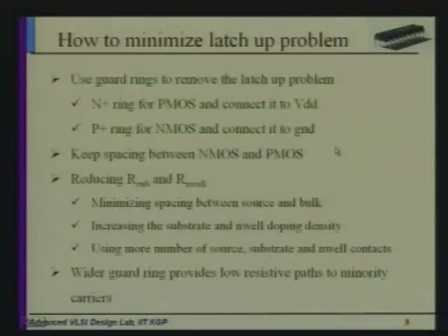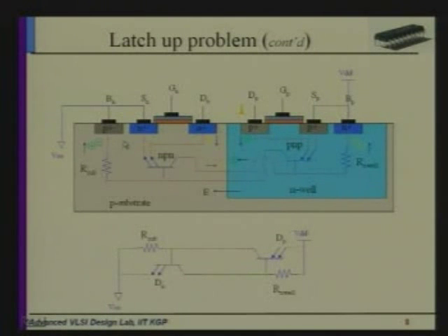I just want to show you the cross section of this. Now consider a simple NMOS. This is the cross section of the NMOS, right? Now consider this is N, and this is P. This is forming one bipolar. So this bipolar will help for the ESD phenomena. If we use the MOS circuit and the pin is connected to here or here, the drain or source region or substrate region, then that will help for ESD.